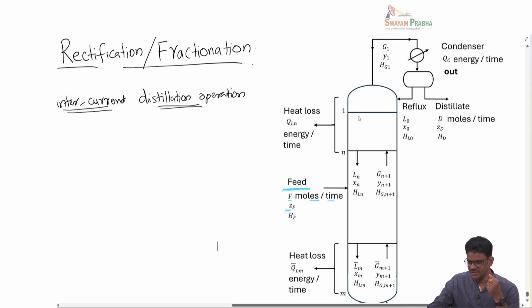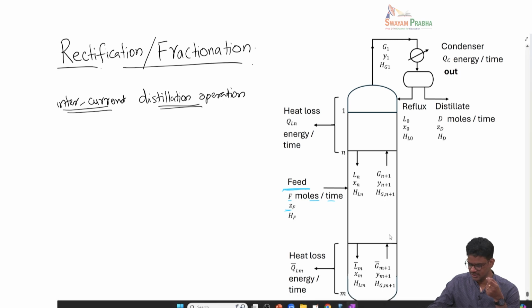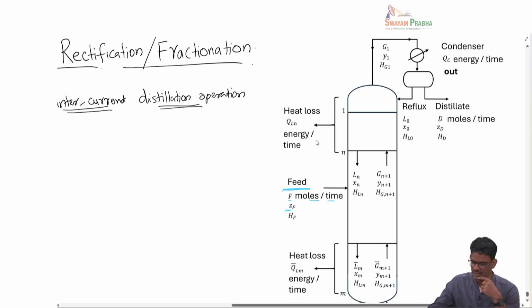And then what you see, this 1, 2, 3, 4, all these horizontal lines in this column, these are basically tray locations. Okay, trays are numbered from the top 1, 2, and so on, all the way down. And what we have here is, once the feed is entered here, it partially gets vaporized and the vapor goes up, okay, because it's much less dense than the liquid.